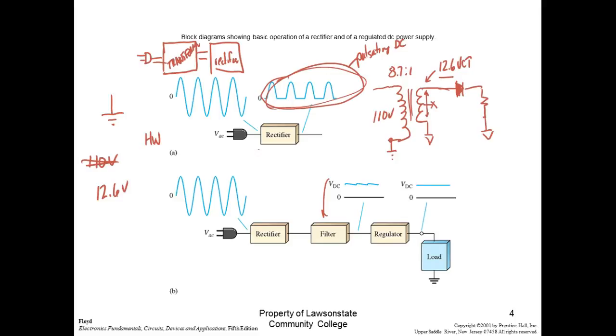Well, this 12.6 volts is not V peak. This is RMS. So we look up at our general AC formulas, and what do I need to solve for V peak? Equation 9. So I'd say V peak would be equal to 12.6 divided by what? 0.707. You can also multiply it by 1.414 if you want to. You get the same answer. So what do we got for VP?